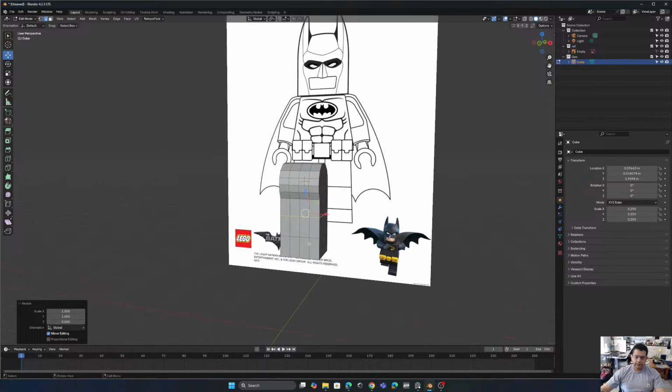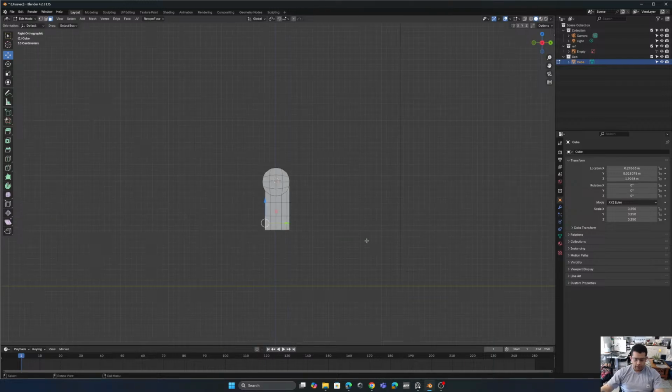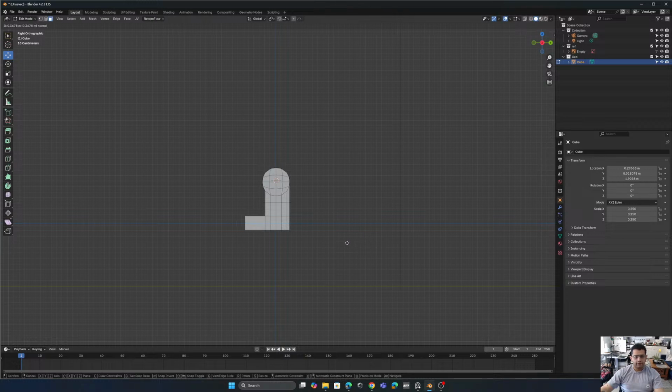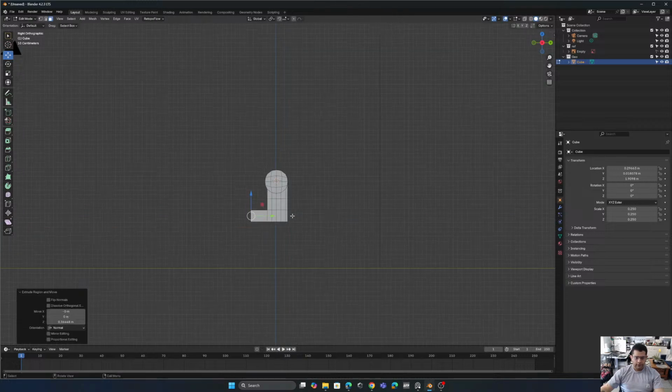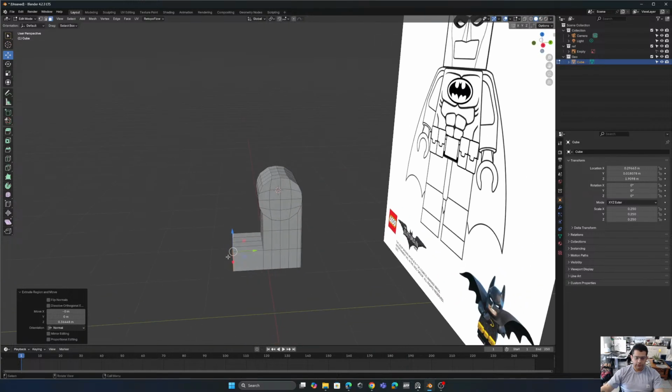After that, we're gonna press 3 on the top number keypad to select faces, or we're gonna press this one over here, faces, and we could select these 4 faces. We press 3 to go to the side view, E to extrude, and we could have the foot. There you go. Right now we have almost the leg over here.